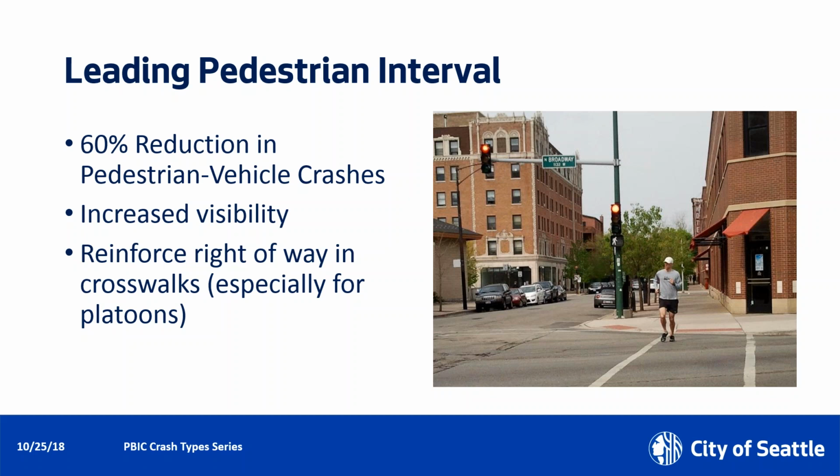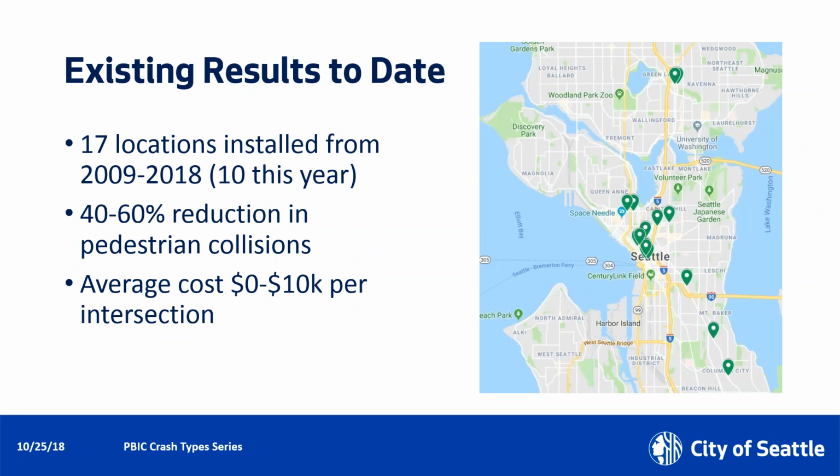This may be especially true for platoons of pedestrians in areas where vehicles might try to jump the green light or jump the red light. They see a large volume of pedestrians and know they're going to have to wait a while to make a left or right turn. And sometimes they may try to jump ahead of that platoon to make that turn. So LPIs are great for that type of behavior.